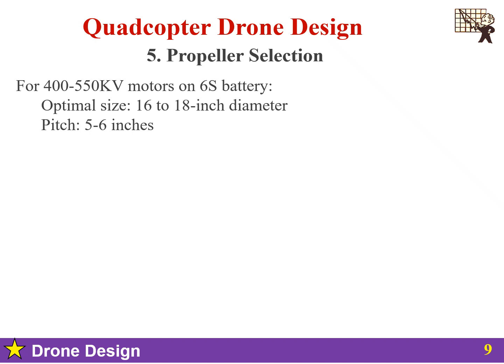The safety considerations. An 18-inch carbon fiber propeller spinning at 8000 rpm carries tremendous kinetic energy. Catastrophic failure could cause serious injury. Quality propellers include factory balancing to plus or minus 0.5 grams, stress testing for crack detection, manufacturing quality control, and recommended replacement schedules. Never use propellers beyond their rated service life or after any impact.